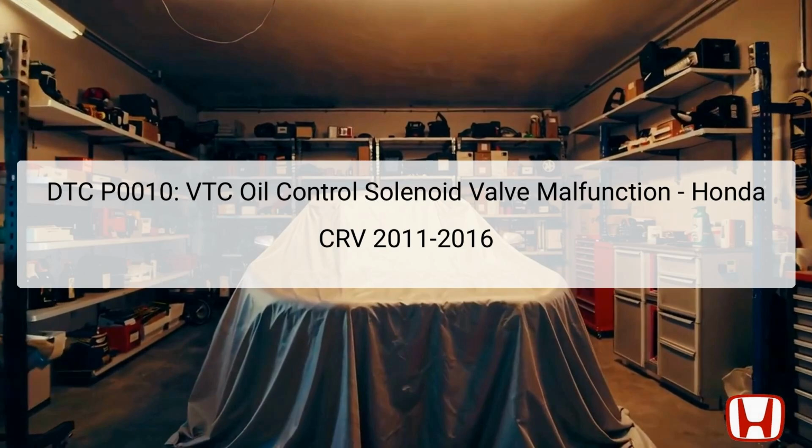The DTC P0010 specifically relates to a malfunction in the variable timing control, VTC, oil control solenoid valve of Honda CRV models from 2011 to 2016. This component is crucial as it adjusts the timing of the engine's intake and exhaust valves based on engine speed and load conditions. The solenoid valve is typically located near the engine cylinder head and is activated by oil pressure to control the variable valve timing mechanism.